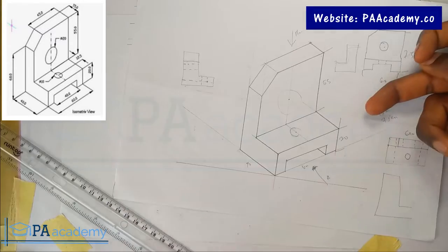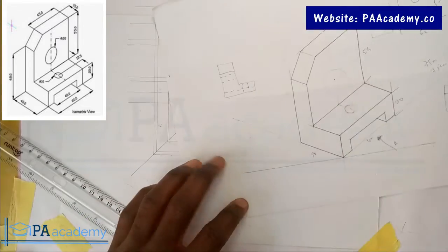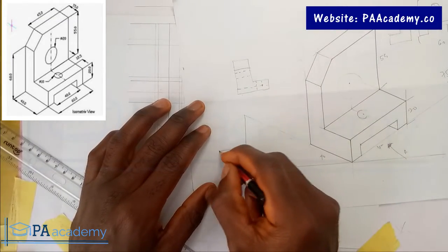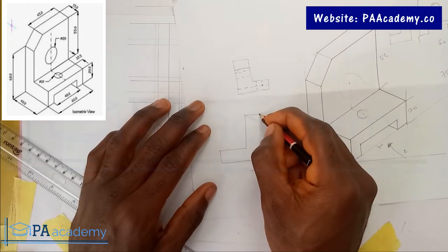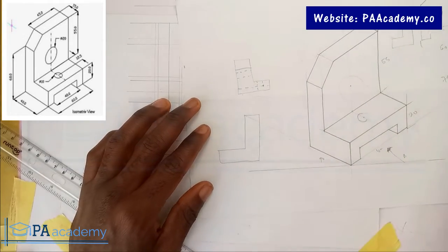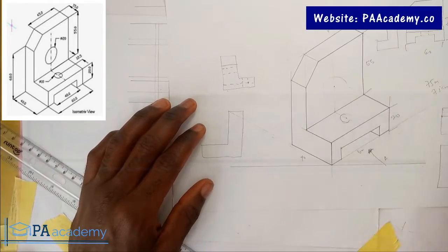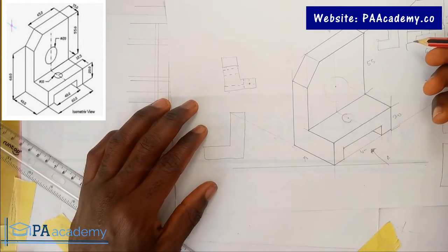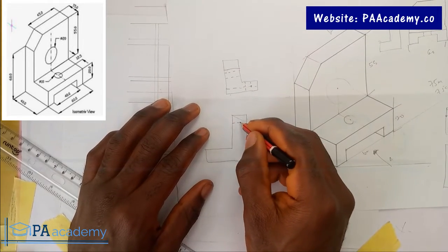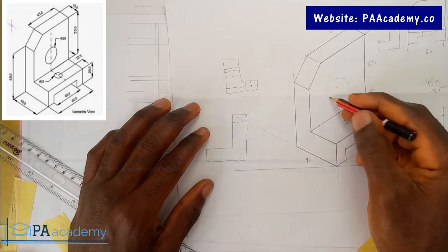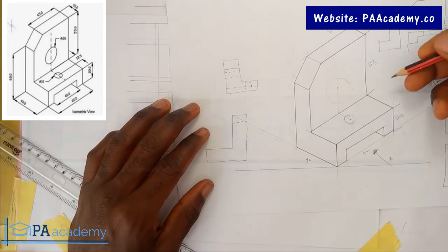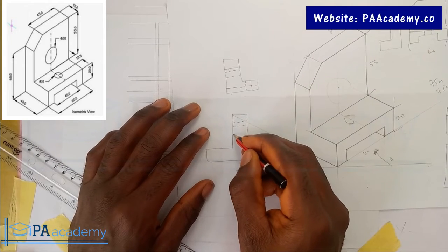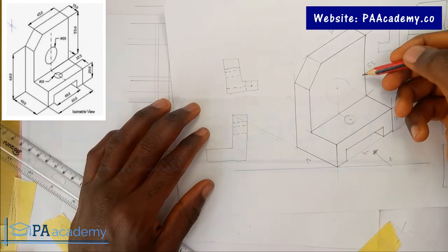So now let's look at it. If you're looking at it from the other side, what are you going to see? So let's just do a rough sketch of that also. So you're going to be having something like this. All right. Then for this particular line here, you're not going to see it from the back, so it's definitely going to be short dashes. Also this opening here, this circle here, you're not going to see it when you're looking from here, so you're also going to indicate it with short dashes. That is a hidden detail.